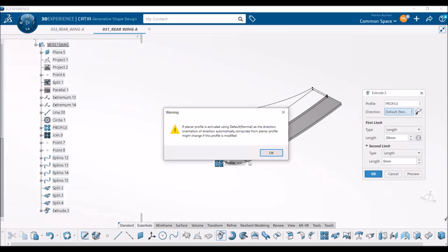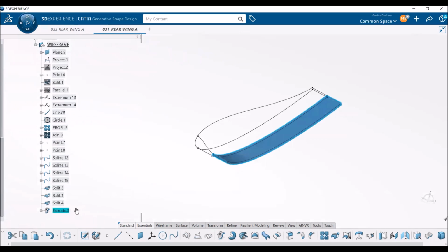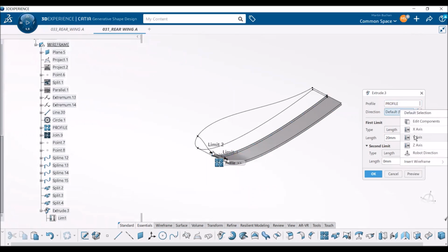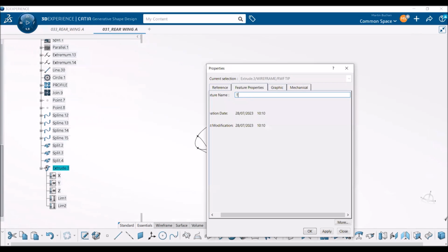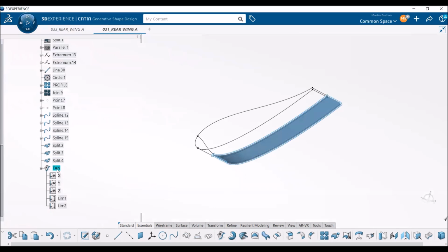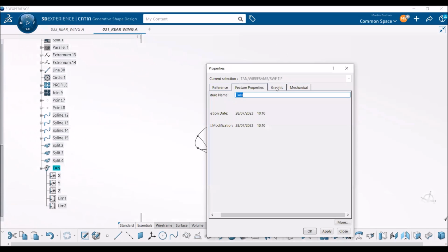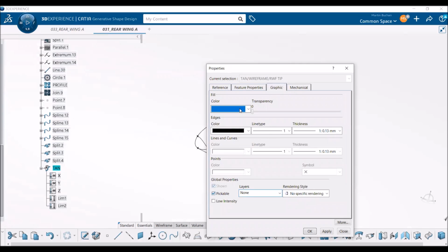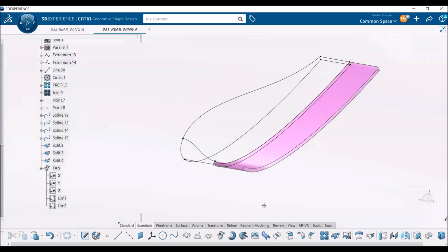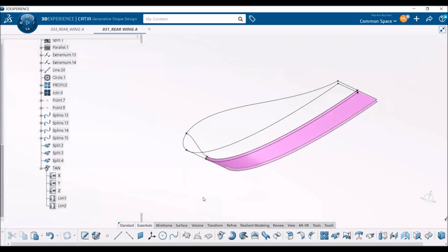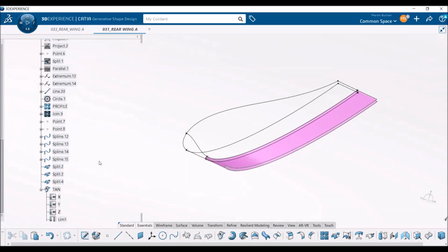And here we create a tangency surface for the outside. So for the new profile, outboard, usually tangency surfaces, I always color them in pink and transparent because it's just very obvious on your screen what it is. You don't really need to read it or something. It's not a construction surface, it's just to help you with building this rather extreme surface. So pink and some transparency. If I see something like this on the screen, I know this is only for tangency reasons. Okay, so that's this feature.